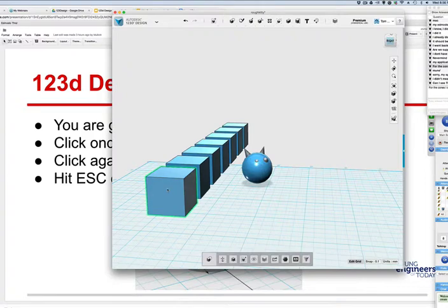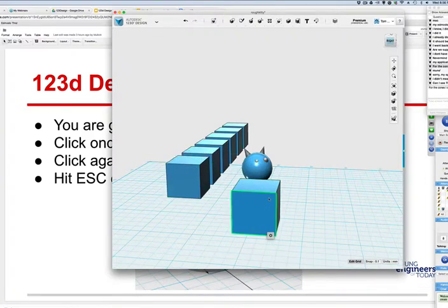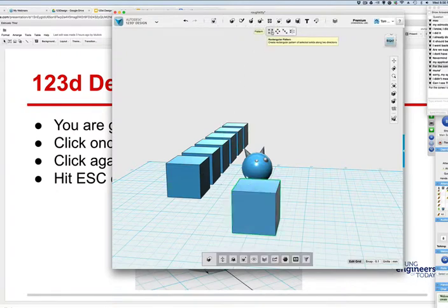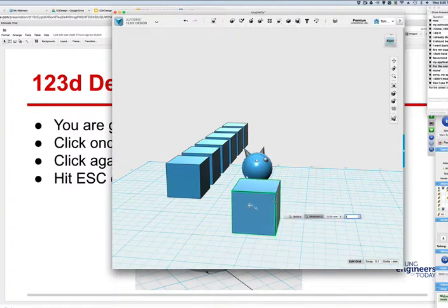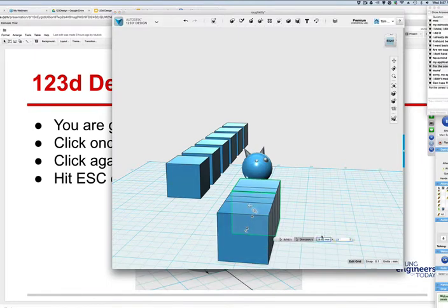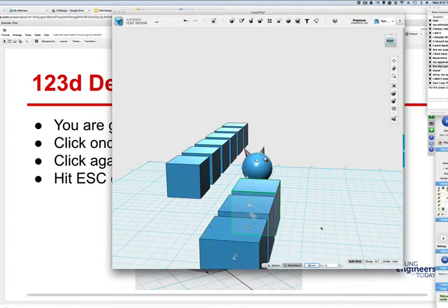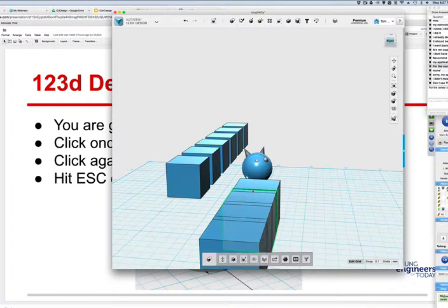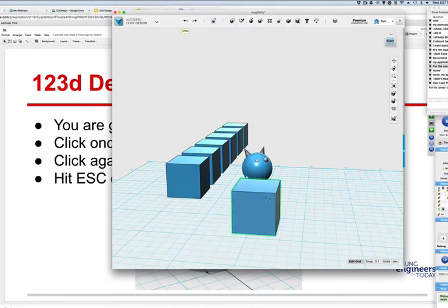And so let's go through it again. Let me just select the object. As we go through this, go here, pattern. We're going to go directions. All right, and then you pull it out. And that's how much space can be between each direction. So you pull out the one, and you can say over here in directions, 50, and then you have 50, and then you can say I want 4, which kind of jammed them in. So you have to keep changing your direction. Be careful when you do that. All right, let me go back one. It should be okay. So here you go.